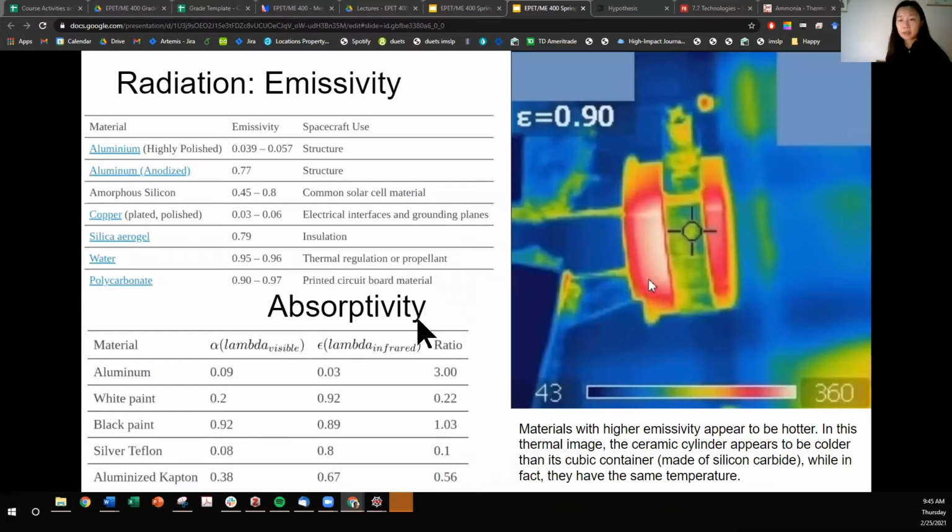Emissivity ranges from 0, a white body that reflects radiation, to 1, a black body that absorbs all heat. Values between 0 and 1 signify a gray body that partially reflects and absorbs at some ratio. Emissivity and absorptivity are both dimensionless values. They are ratios. Absorptivity of the surface of a material is its effectiveness in absorbing radiant energy.